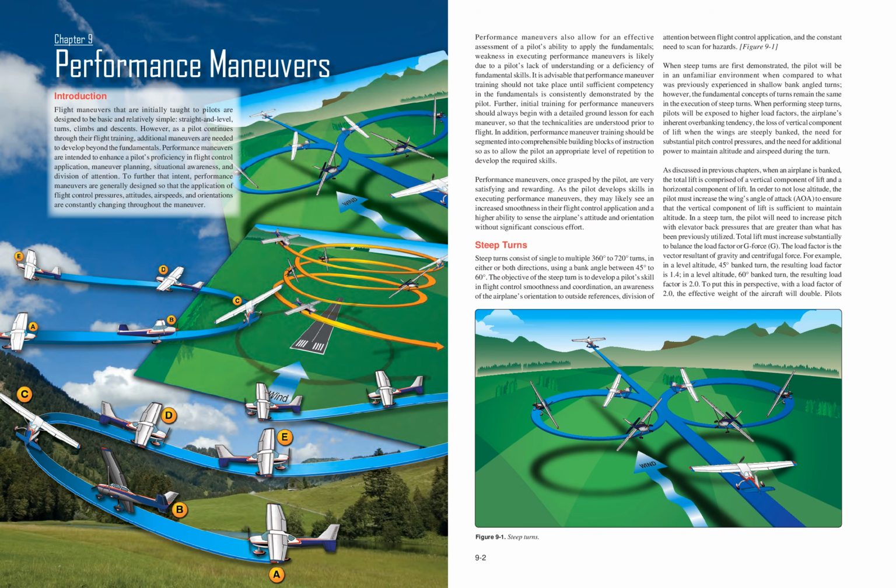When steep turns are first demonstrated, the pilot will be in an unfamiliar environment when compared to what was previously experienced in shallow bank-angled turns. However, the fundamental concepts of turns remain the same in the execution of steep turns. When performing steep turns, pilots will be exposed to higher load factors, the airplane's inherent overbanking tendency, the loss of vertical component of lift when the wings are steeply banked, the need for substantial pitch control pressures, and the need for additional power to maintain altitude and airspeed during the turn.